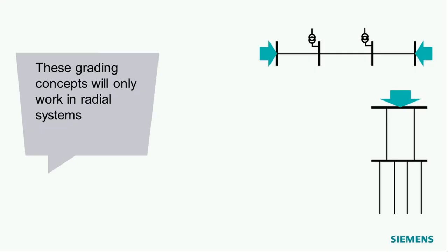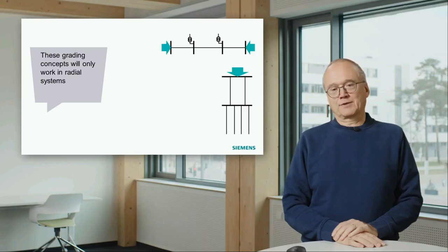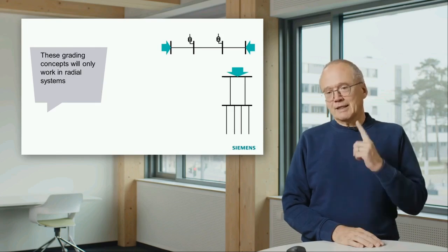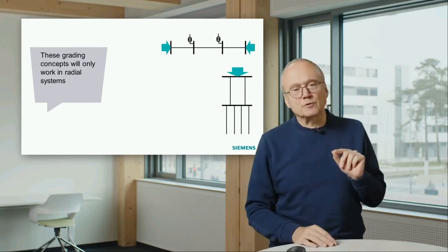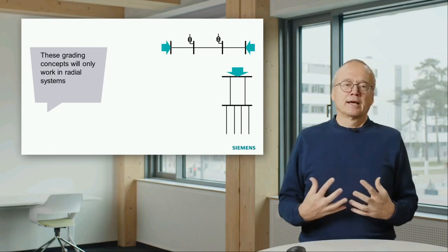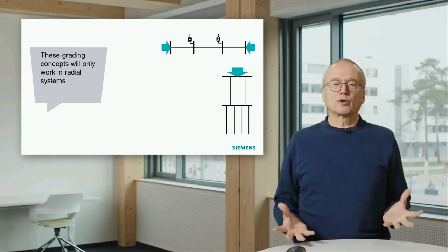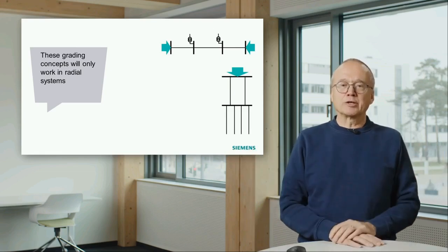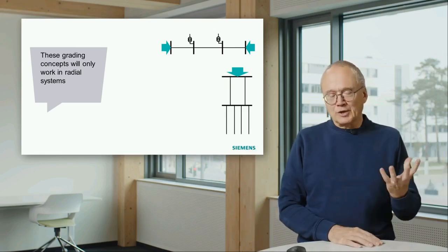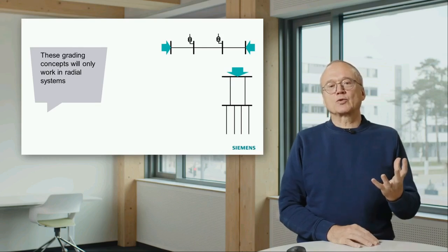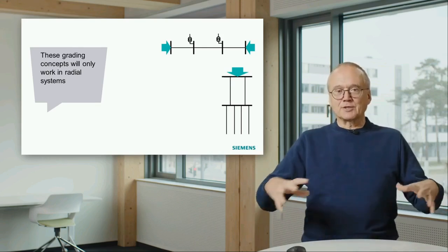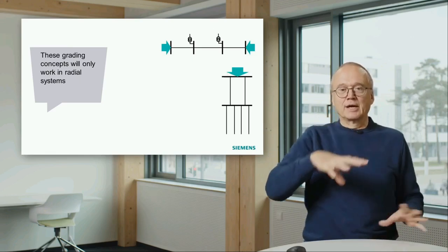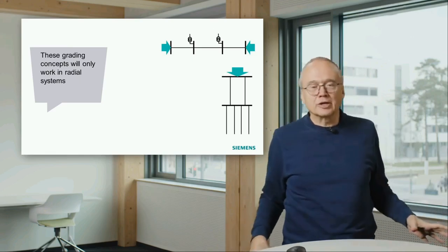It's a mesh system because in one location we have 2 cables or 2 lines in parallel. Or sometimes you also have things like that. You have a feeder, but you have infeeds from both ends. That is also a thing which sometimes has to be considered in conjunction with the conversion of our systems, where we implement more and more renewables. With that, you can also end up in a situation that you had a radial system with infeed from one side, and now you install renewables.